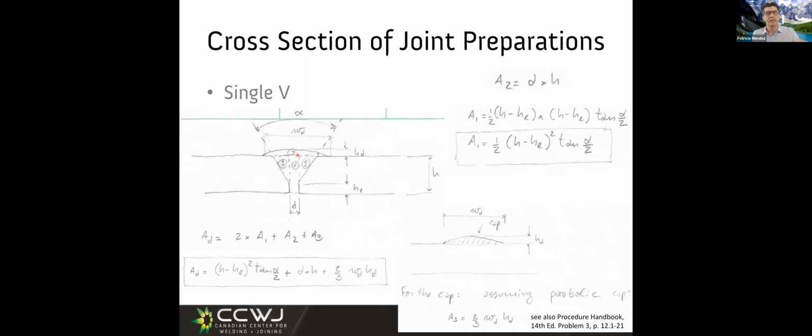However, that base metal that was molten, I didn't put it, it was already there, and it remelted as I was welding. I don't need to account for that material for the mass balance. So all we need to account for to do a mass balance is the joint preparation, which we know from the drawings. So we're in great shape because we have close to nothing empirical here, all calculated with the basic algebra of high school.